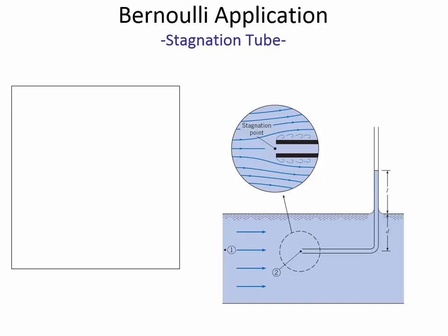So let's look at this picture and try and diagnose what's happening. It's similar to one of the examples we looked at in class last time, where the streamlines are going along. They're indicating the direction of flow. What does it mean that the streamlines are parallel? It means uniform flow. It means that the velocity isn't changing with respect to position, except that between 1 and 2, one of these streamlines finds a dead end, because the water is flowing through the river, but then the water inside of this tube is static.